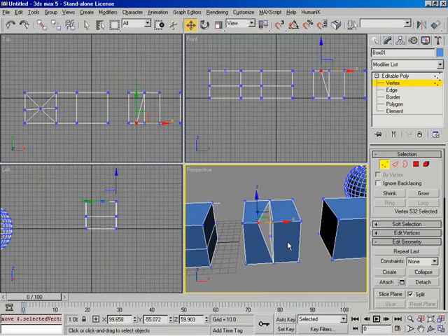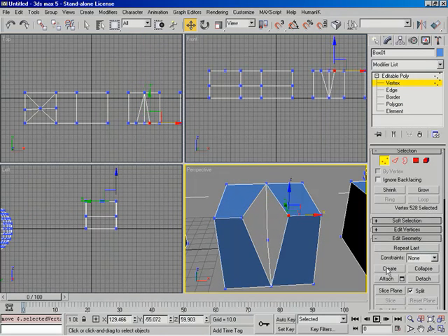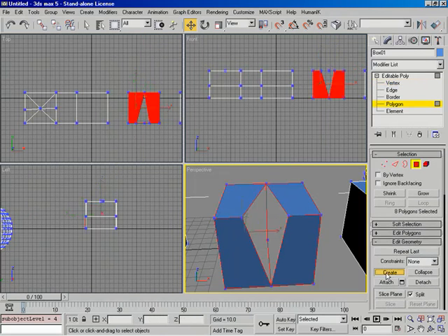So let's go ahead and use some of the tools that we've seen. I'm going to open that one up. Let's grab this one right here. Open this one up a little bit more. Now I'm going to come back up here to Create. Let's switch over into Polygon mode. Back to Create. And I'm just going to go from here, here, and double-click there.